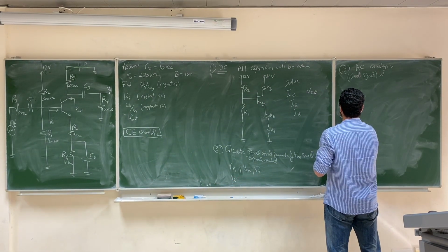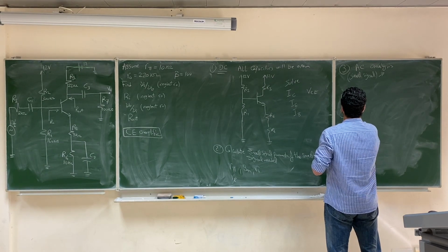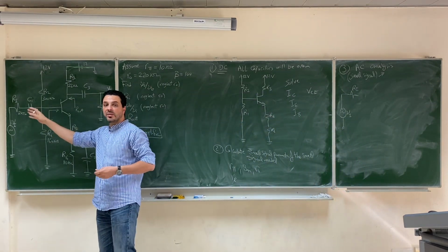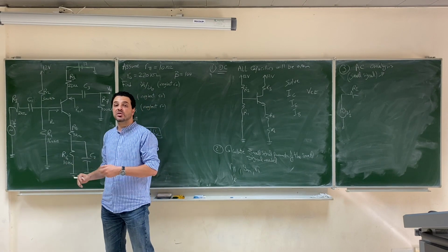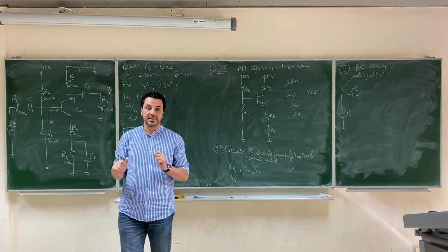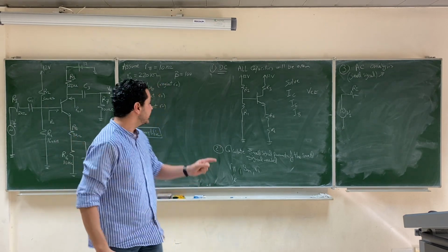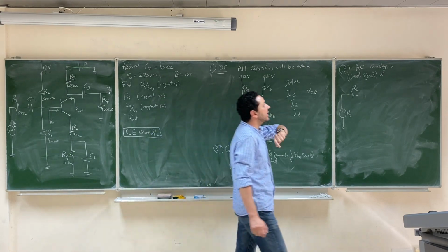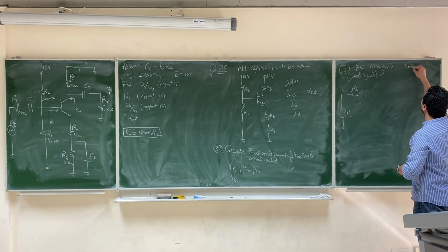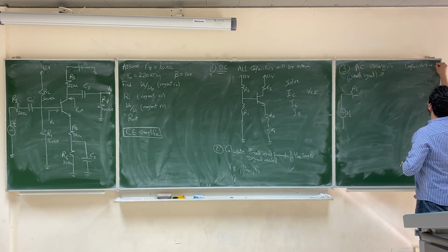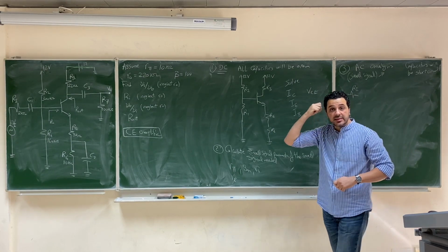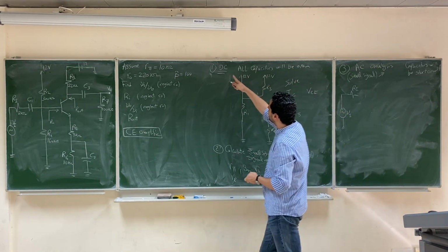First, we have an AC source. This is the input connected to our input. And then we also said that all the capacitors will be considered short circuit in the AC analysis. So the capacitor for the DC appears as an open circuit, like in this case, where the capacitor was an open circuit. In the AC analysis, all capacitors will be short circuit.